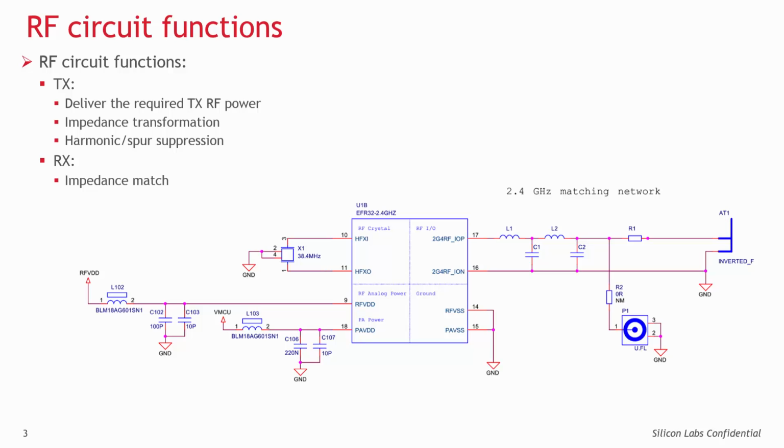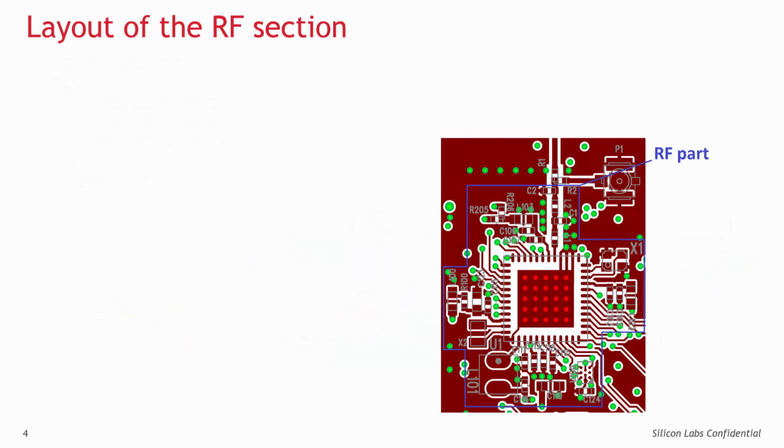Examples shown in this video are based on a general 2.4 GHz EFR32 radio board. The main layout design concepts are shown with this reference layout to demonstrate the basic principles. Although these rules will be shown through a design that uses a 4-element matching, similar design practices should be applied with a 2-element matching network as well. For low-power applications below 13 dBm, a 2-element LC network is sufficient, while high-power solutions above 13 dBm require a 4-element match.